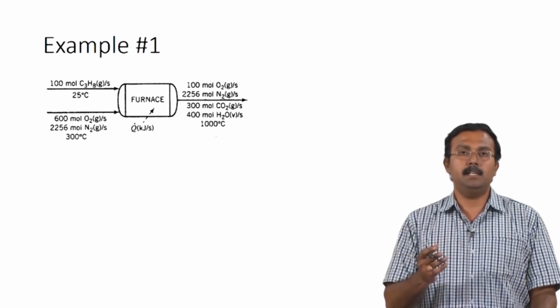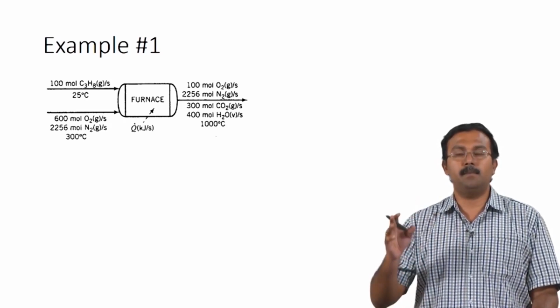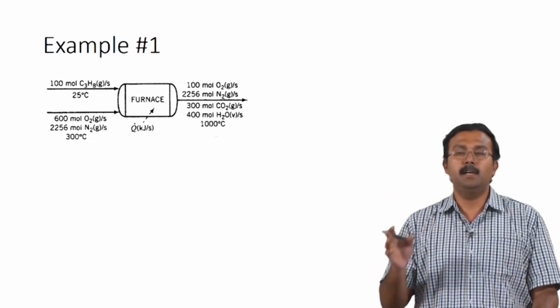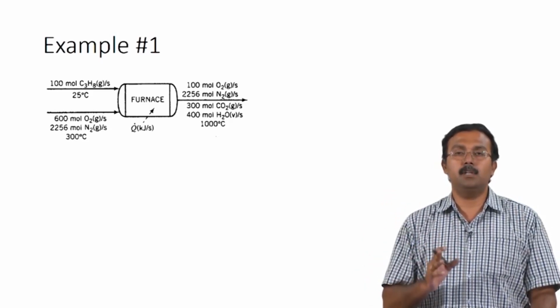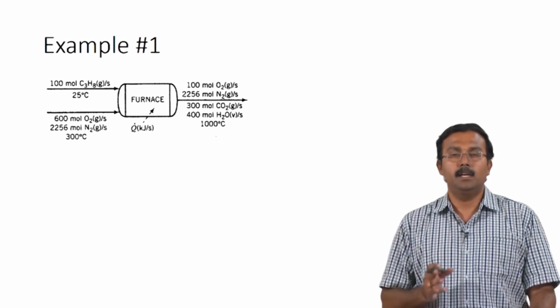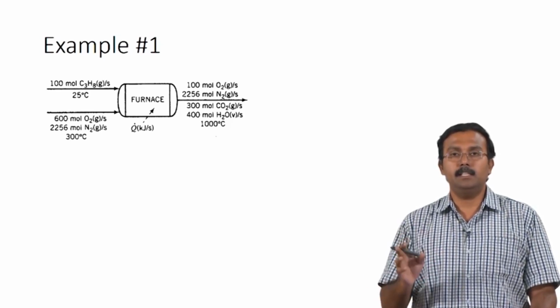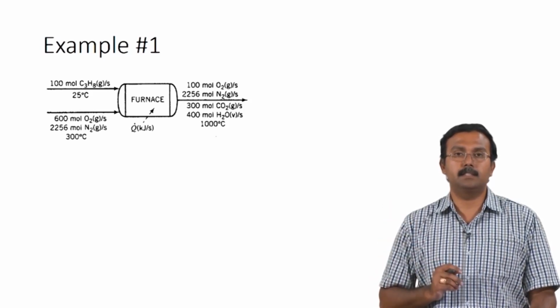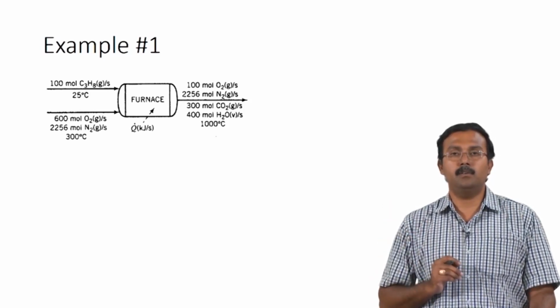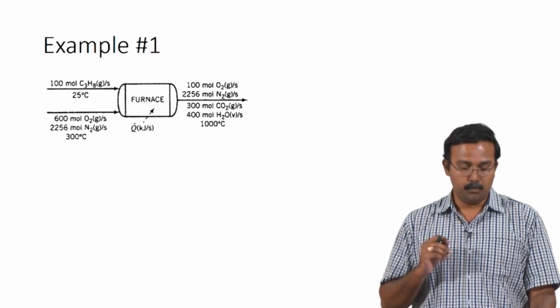After we get these values, we will plug them back into the specific enthalpy table, calculate the total specific enthalpy of the outlet stream and the total enthalpy of the inlet stream, and find the difference to understand the total change in enthalpy. However, in addition to these two, you also have to account for the heat of reaction. How do we account for it?